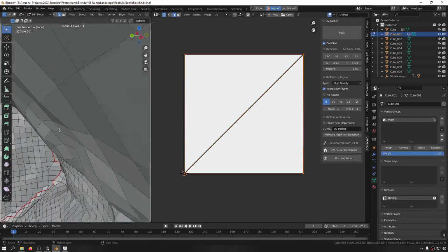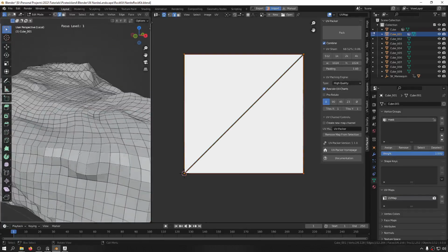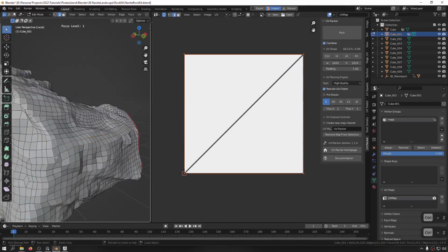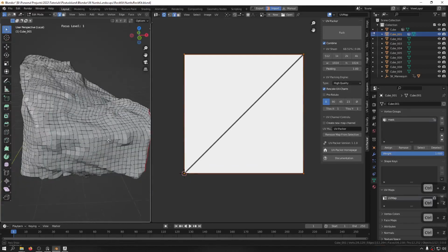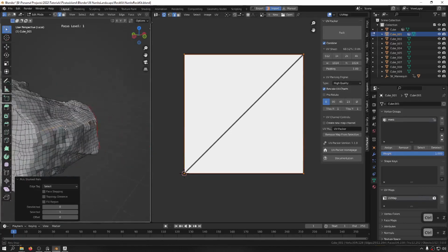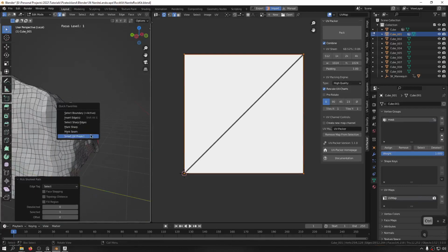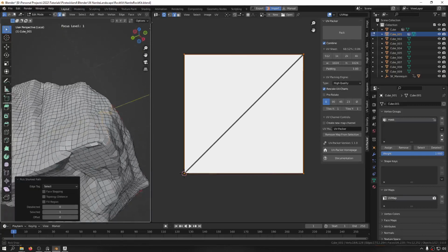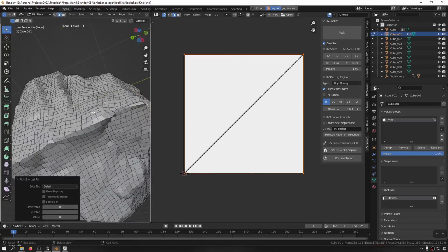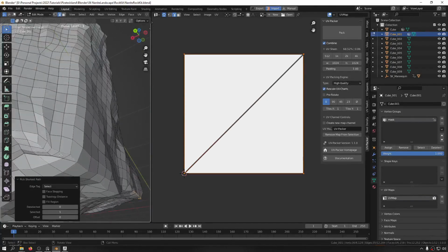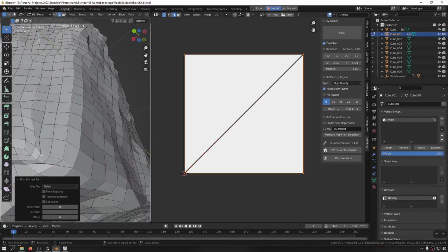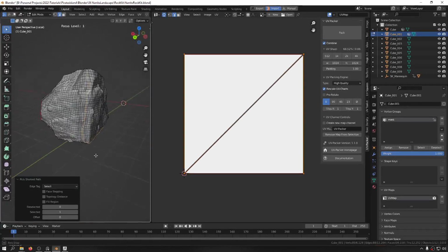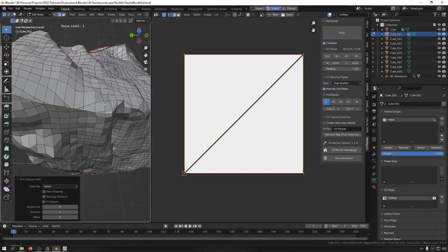And now select from this part and try to follow the curvature. Okay, and let's follow from here. Now let's go a couple of steps back and now follow from here. And trust me, UVing something like this is going to be a lot easier than UVing, for example, a mesh that has something like a couple of million polygons. Okay, it might look a bit overwhelming, but it's a part of the process and you cannot really dodge that. So let's continue all the way to here and to here as well.